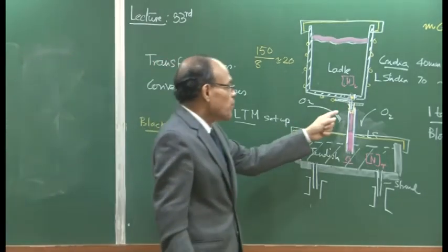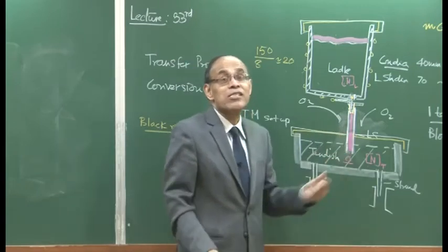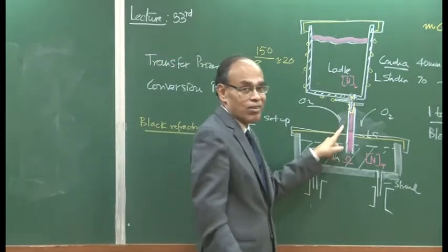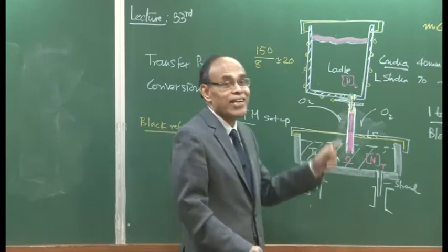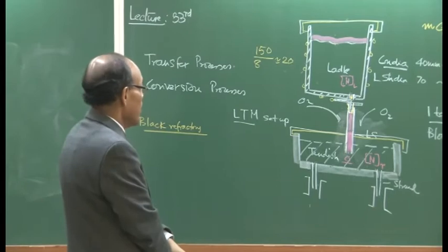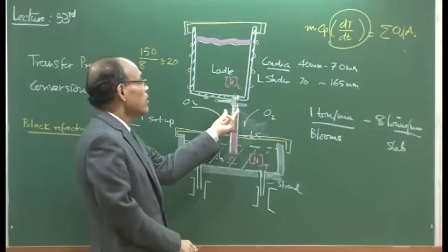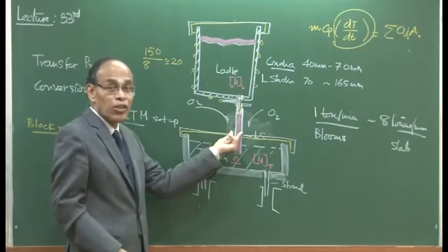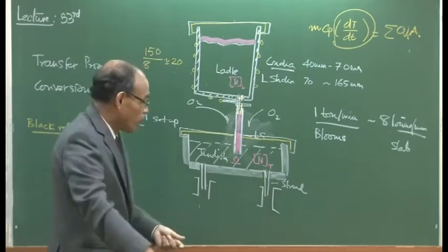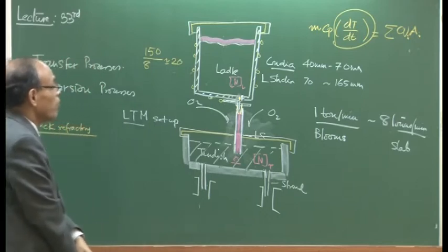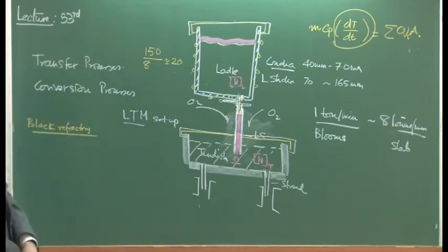So, we can transfer molten metal. No steel plant which is producing quality steel will do open stream casting. Everybody will be using a ladle shroud. It is almost a standard artifact in the steel industry and is very vital during the transfer operation. It is coupled with the collector nozzle, and the quality of the refractory matters, because molten metal is accelerating and flowing down at large speed. So, there is a good chance of erosion of refractories, and these refractories have to be good, otherwise steel can be contaminated with what is known as exogenous inclusion, which I have already said.